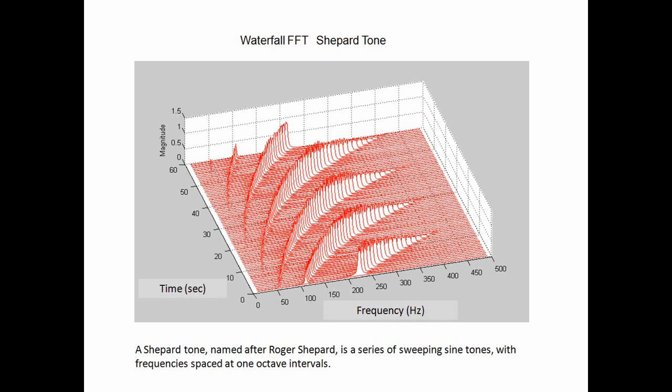No. If we had pure sine vibration at a steady-state amplitude, would we do a Waterfall FFT? No. But if we have these cases, which do occur sometimes in nature and sometimes in our rocket motors and our music, where the parameters of frequency and amplitude change with time, it's a wonderful and fun tool to use.